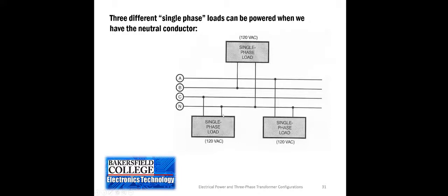Well, the problem happens if each of these loads had a different amount of current draw on the transformer, then you would have a neutral current. Now, how you calculate that neutral current, you can't just add them up because you have 3 phases that are part of the power line, but then you're pulling from one phase to neutral.